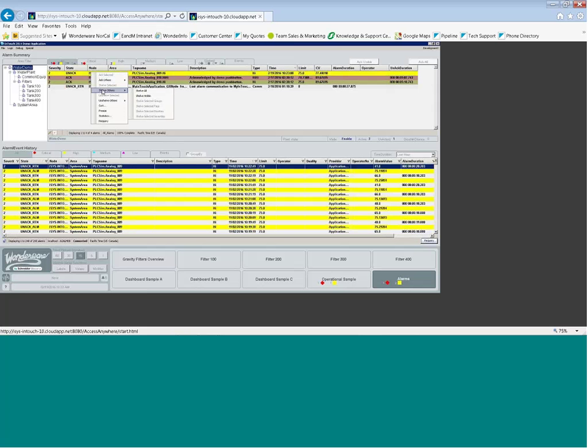Shelving alarms means putting them on snooze. If I know that there's some maintenance going on on that piece of equipment, I can say, let's shelve it for 4 hours because we're putting it in maintenance, and then that alarm will automatically activate after 4 hours. I don't have to remember to come back and enable that alarm again. So it really helps with getting rid of those nuisance alarms.